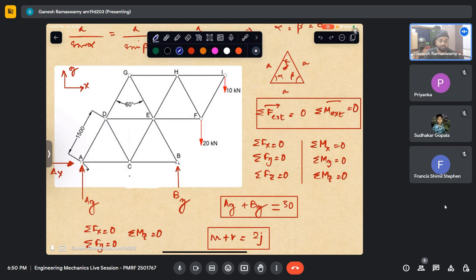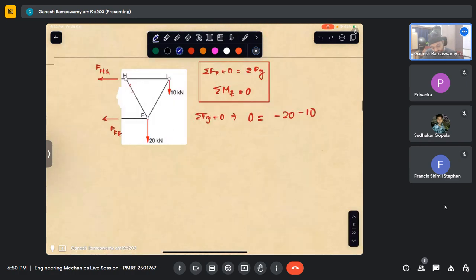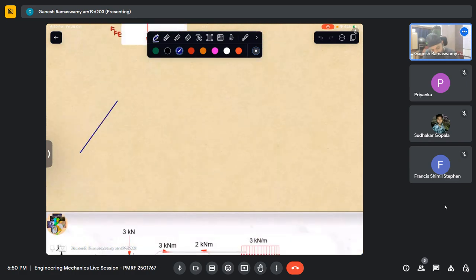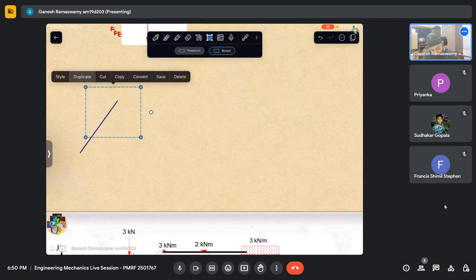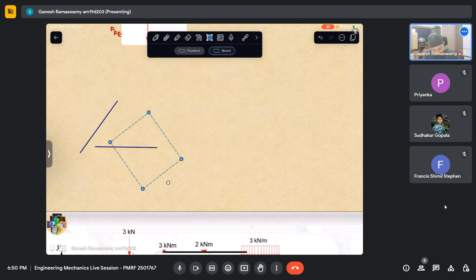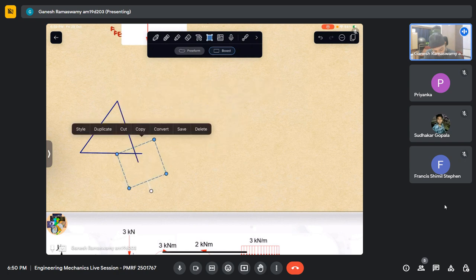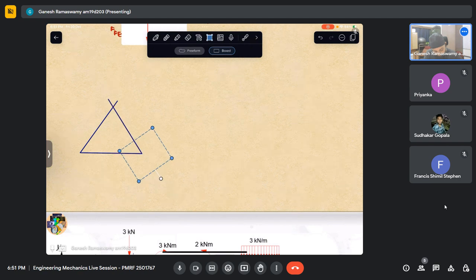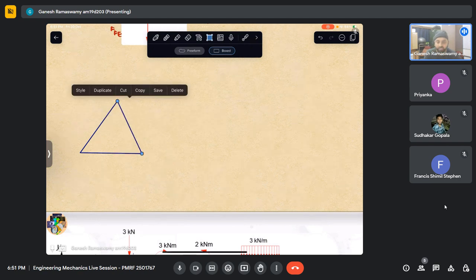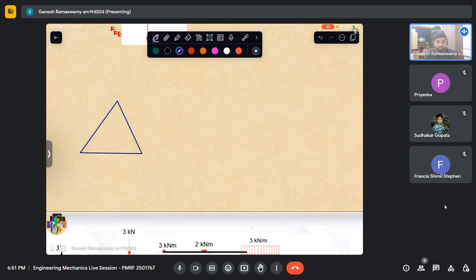And there is a reason behind that. See, if you take two members, let us say I connect two members like these, both of these can rotate about this. They are having some rotation. Now let us say I bring in a third member and connect these two, something like that. If I were to connect these two, now the movement is totally arrested. Relative movement. Anyway, one would have to be grounded. That is a different thing. But I'm saying the relative movement gets arrested.